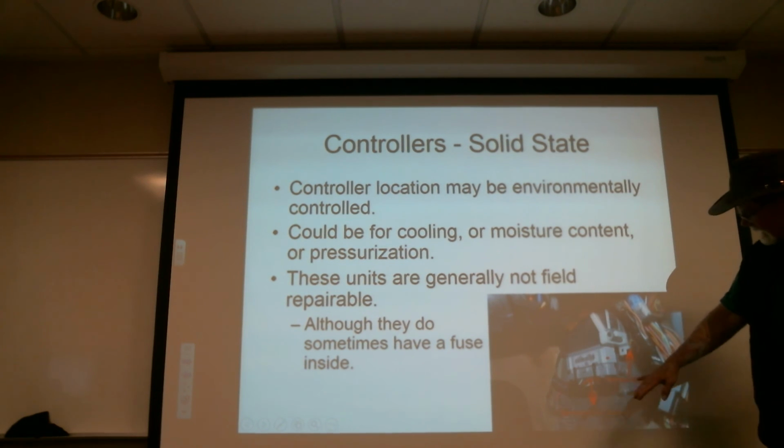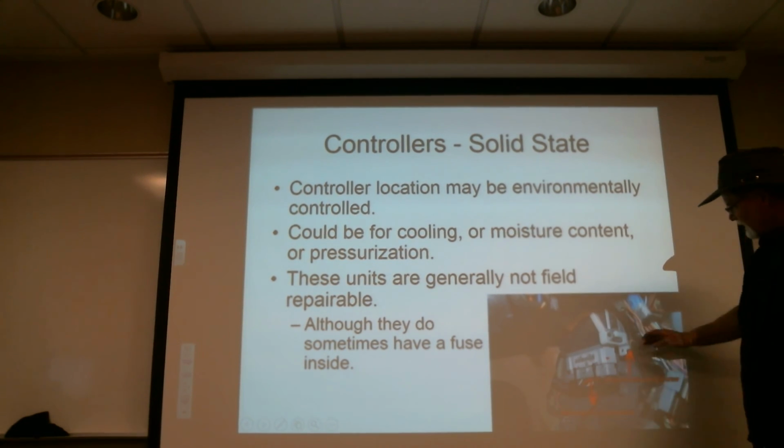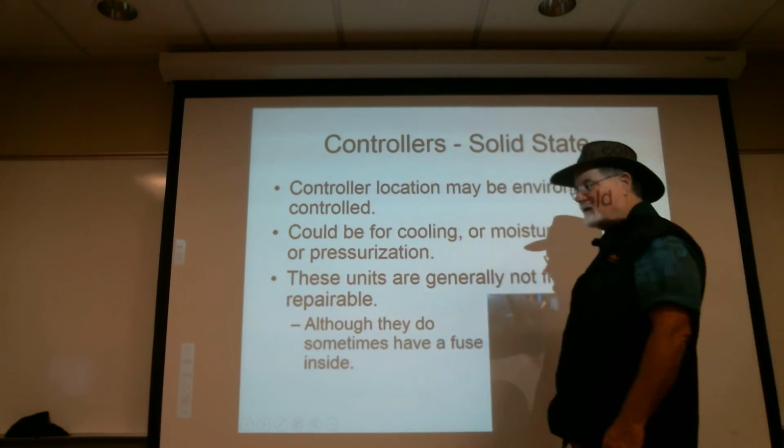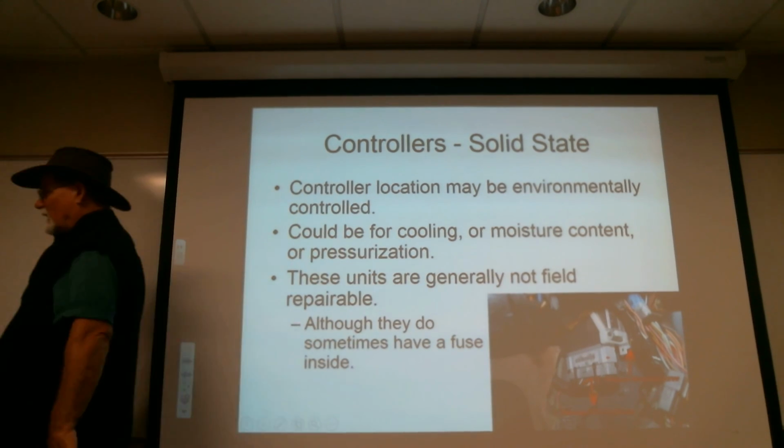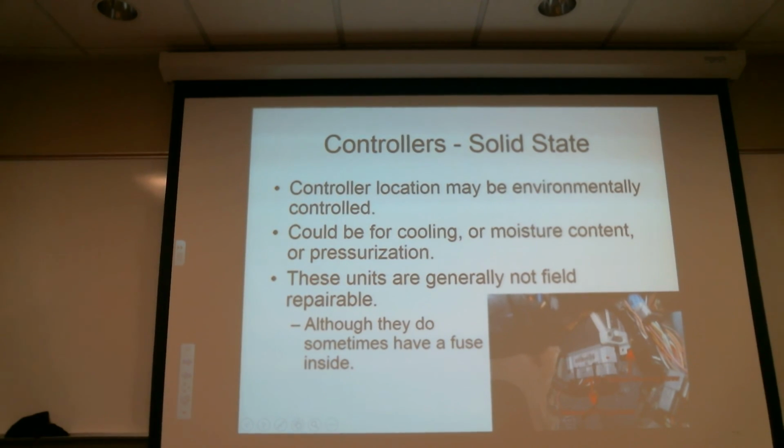So in this particular case, it's like remove the screws, remove the connectors, do some stuff, and out it comes while you're upside down laying on top of the seat, hating life. Of course, what's probably sitting right above that thing is the heater core. And so after a few years, when it finally blows out, it spews coolant, hot coolant all over that puppy.